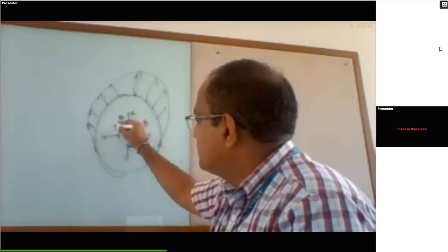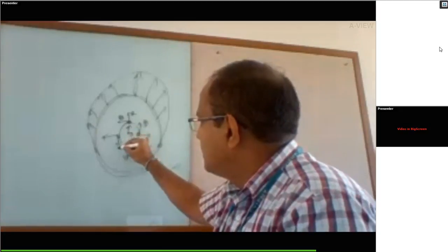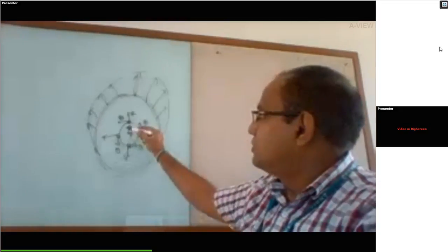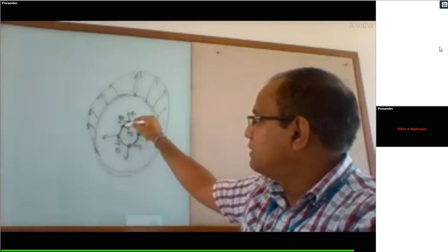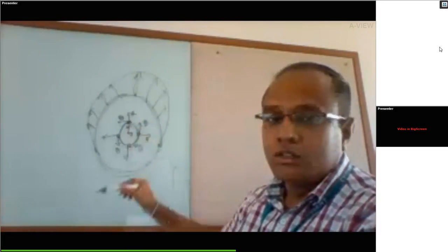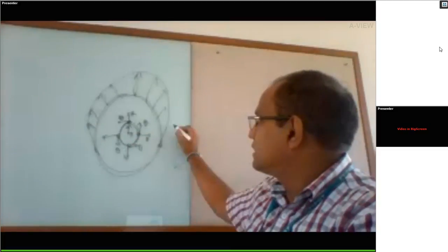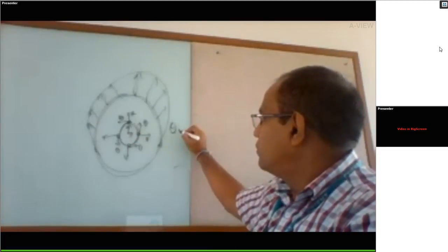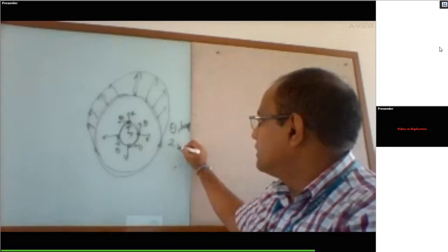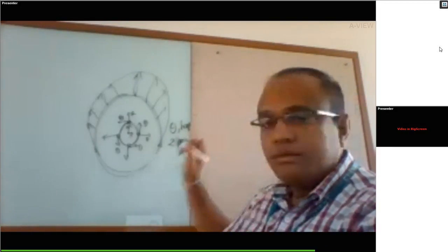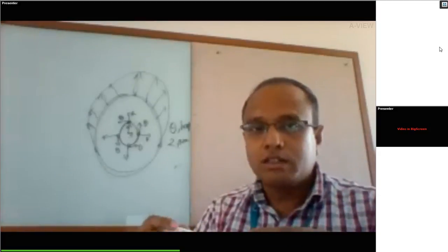Theta is always tangential to the nodes. So we need to constrain theta, or hoop, and axial. These are the constraints we need to give on this problem.